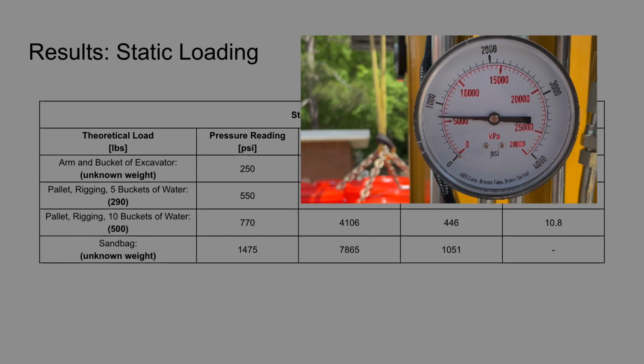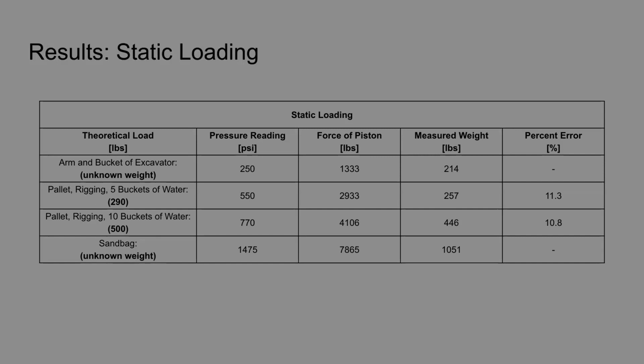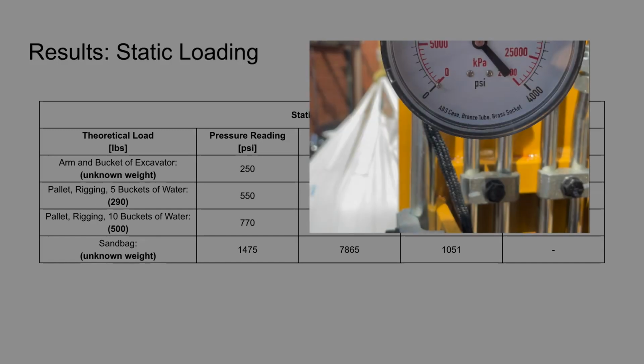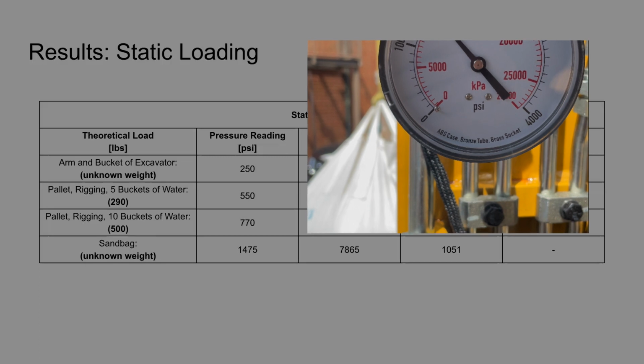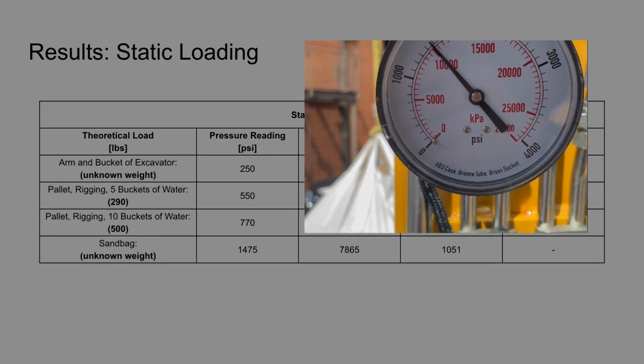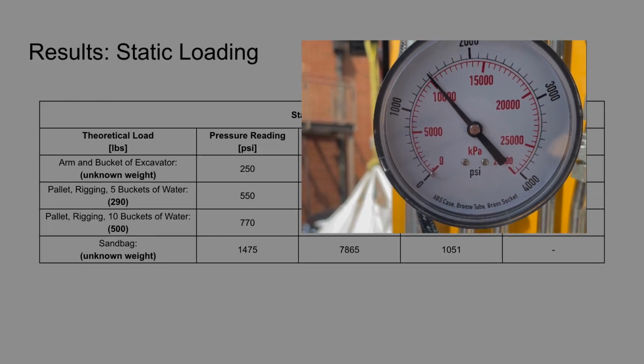Lastly, we decided to lift up the sandbag, which had an unknown weight, and this gave a pressure reading of 1,475 psi with a force on the piston of 7,865 pounds, and we calculated the weight here to be 1,051.